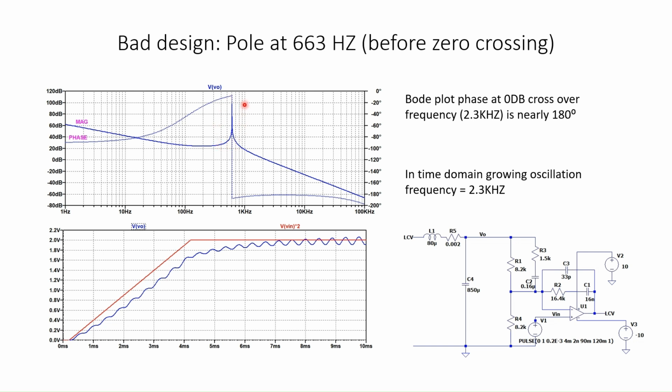So now after the resonant frequency, we have two poles of the plant RLC circuit, and one pole we just shifted from here to here, and one zero of the compensator. So 3 poles, 1 zero, net 2 poles, that is the magnitude will be falling at 40 dB per decade. We can see that the slope is 40 dB per decade here and continues to fall at the same slope until the next pole, which is after 100 kHz.